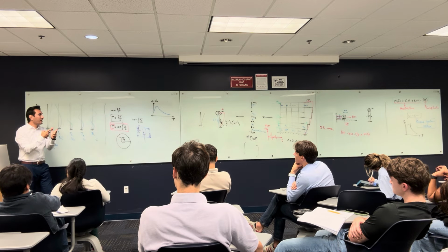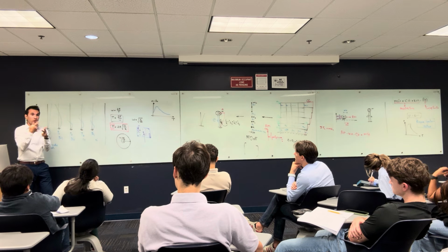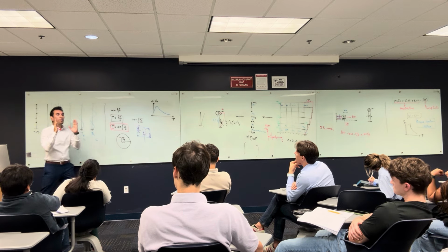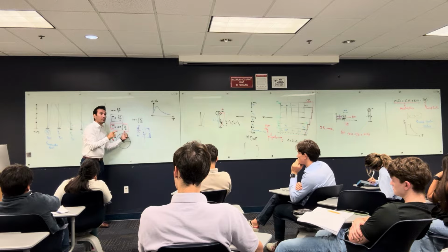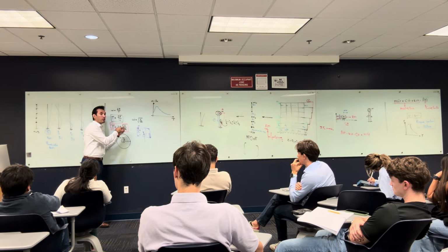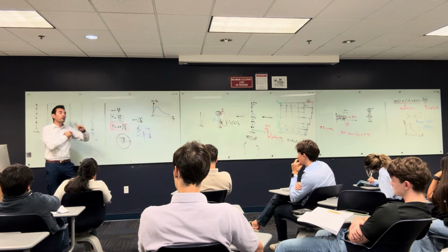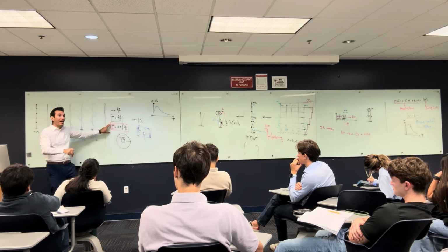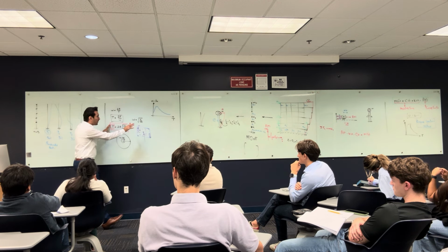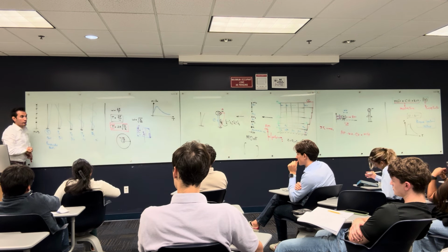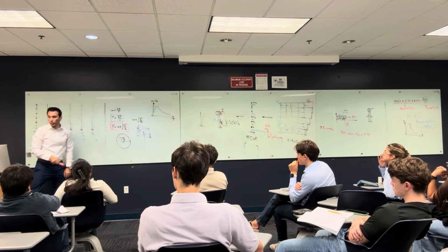Does it depend on the mass? Does it depend on the force that is going to be applied to the structure? No. It depends on the characteristics of the building. It depends on its mass and stiffness. And by the way, the same equation does exist if you include the damping. This is called the undamped period. If you have the damped period, you are going to see the damping coefficient somewhere in the equation. But I don't want to overwhelm you with a lot of equations. Let's focus on this one.